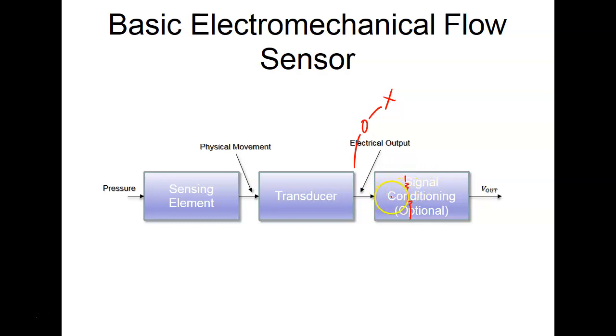which basically we can come in and set a threshold. And sometimes it's actually adjustable. Sometimes you can adjust where it trips. A good example is this pressure sensor. I can change when output 1 and output 2 go. If I'm going to go digital, this is going to be a threshold detector, right?